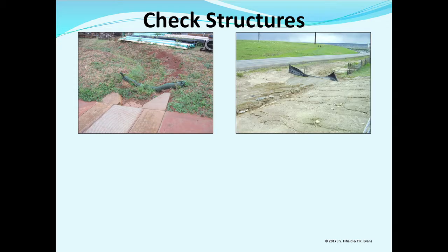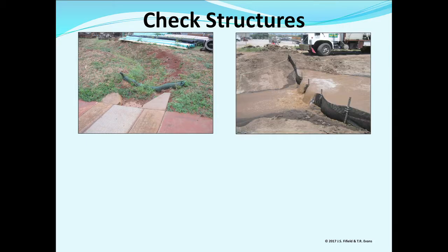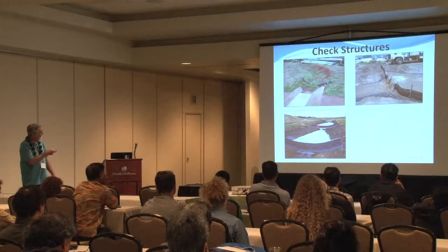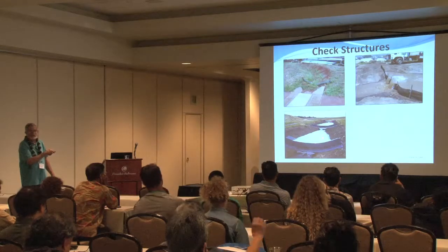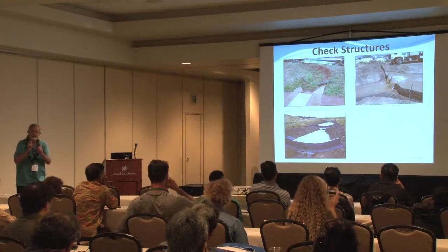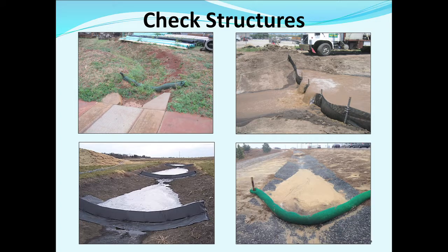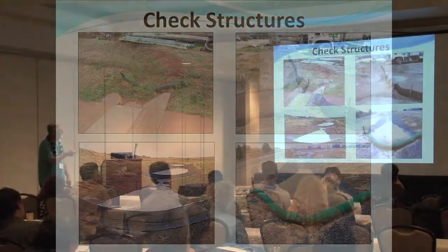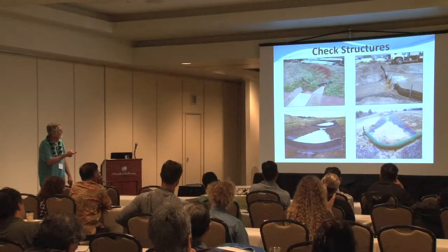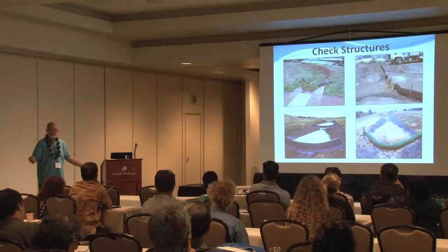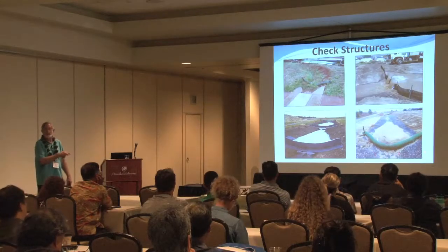So, that, bad news, everything went around. You don't like that. That's okay if it's installed right. Here's a series of them that you try to look for. This would have been better if that one would have been a little bit closer so the water could cascade off from the top one onto the bottom pond. That is erosion control. So you got the sediment control, you got the erosion control, depending on what you're using it for. Having an erosion control blanket in a drainage channel, turf reinforcement mat we call it, is the best thing you should use, and this is probably a waste of your money.